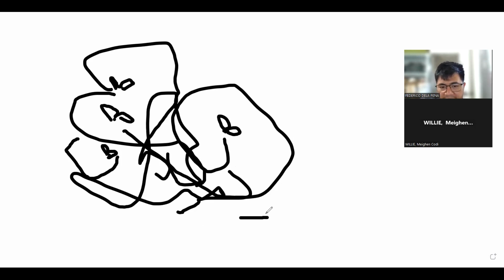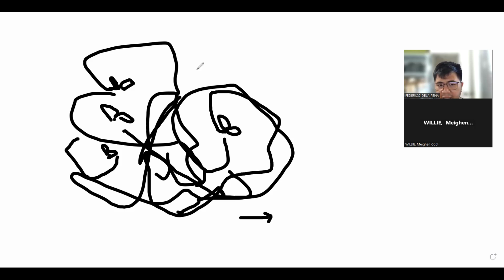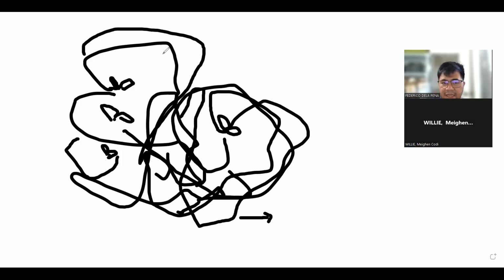But as a group, they might actually be moving slowly. So the individual movement of the flies is similar to the seepage velocity. If you look at their individual movement paths, they can move very fast. But if you look at them as a group of flies moving in a certain direction, they might be moving very slowly as a group. And that is analogous to the Darcy velocity.